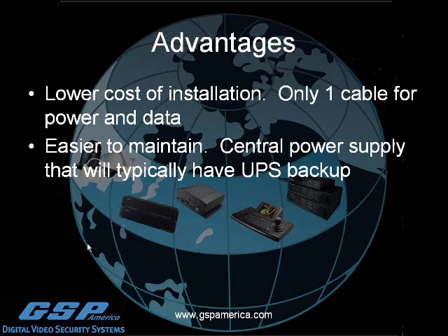The other advantage, from an easier to maintain perspective, is that with a central power supply, typically you're going to have a UPS backup, so that if power ever went out to your facility, the UPS backup would kick in and you would still maintain all your devices powered. Particularly with cameras, if you were to lose power, your cameras would still be powered. You'd still have recording going on of anything at your facility. So those are the main advantages of POE.